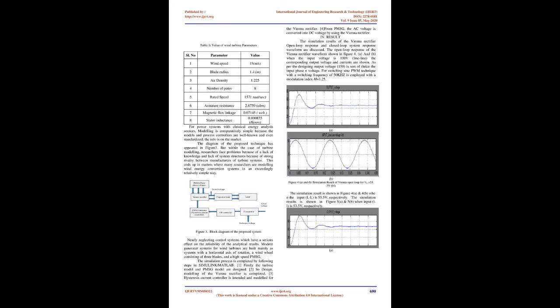Fuzzy inference is shown in Figure 2. Fuzzy inference is the method of using fuzzy logic to formulate the mapping from a given input to an output. The mapping then provides a basis from which decisions can be made. Within the fuzzy logic toolbox, two forms of fuzzy inference systems can be implemented, Mamdani type and Sugeno type. These two forms of inference systems change slightly in how outputs are calculated. Fuzzy inference systems in fields like automatic control, signal processing, decision analysis, expert systems, and computer vision are successfully applied.